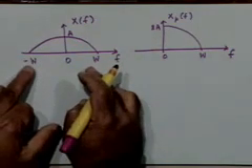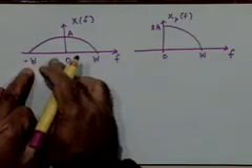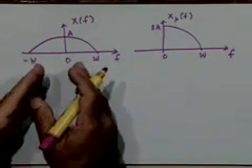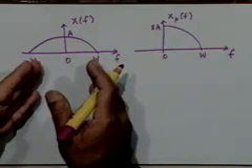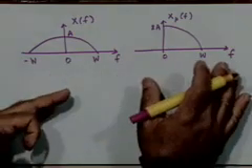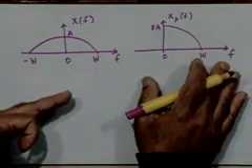The real signal has both negative frequency components and positive frequency components. This spectrum would be amplitude even symmetric, the amplitude spectrum would be even symmetric, and the phase spectrum would be odd symmetric. The complex signal that we have constructed, the analytic signal, only has positive frequency components, just like the complex exponential. It has only a positive frequency component.